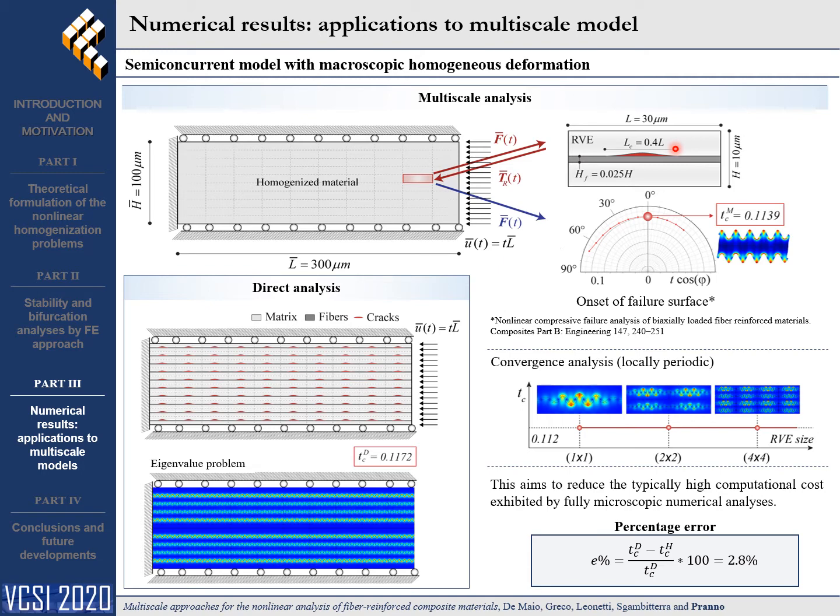In the meantime, the macro deformation state of each microscopic cell has been monitored by means of the two-dimensional stability and uniqueness domain. A convergence analysis to the RVE sides has been incorporated in the numerical procedure in order to verify the coincidence of the mode shape and the critical load level between a single cell and a cell assembly of increasing dimensions, and the obtained critical load factor is equal to